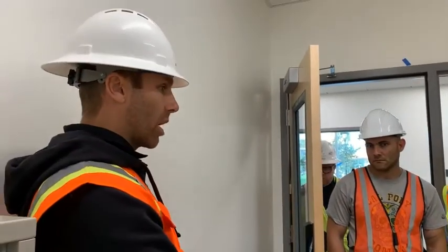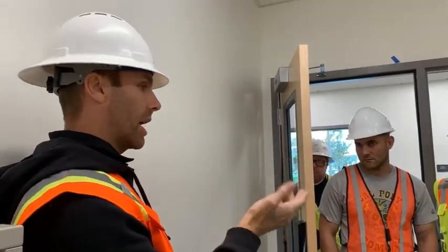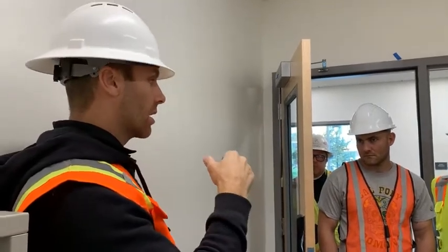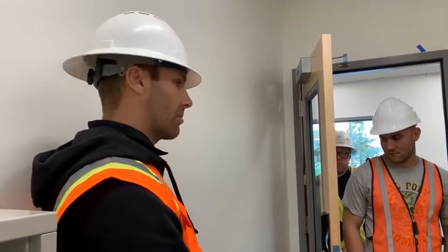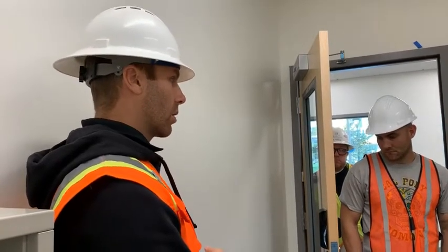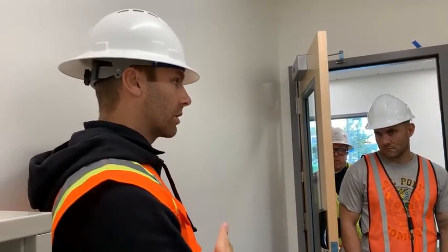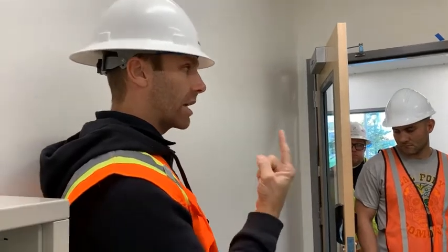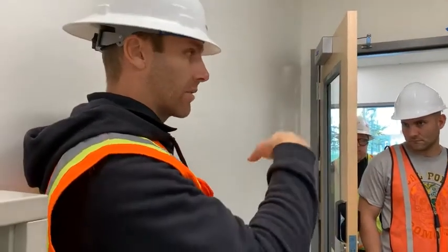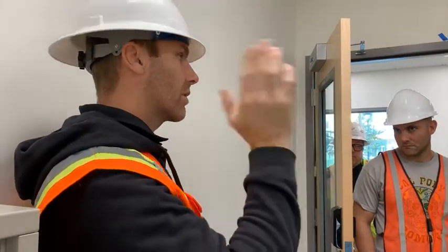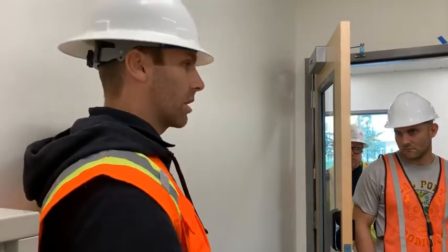That receptacle will be hot. Once you leave the room and it times out, there's no occupancy, everything's off, then that receptacle will go off. Same setting, 10 minutes, okay? So whatever the lighting is, the receptacle is, because the sensor itself has the time delay set on it. Dim at 7.5 minutes. After everyone's left, 2.5 minutes later, the lights would be off, the receptacles would be off,